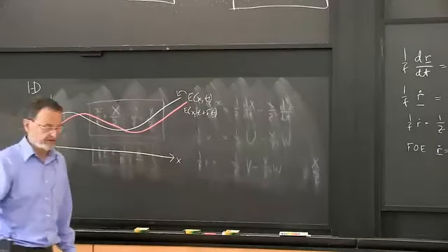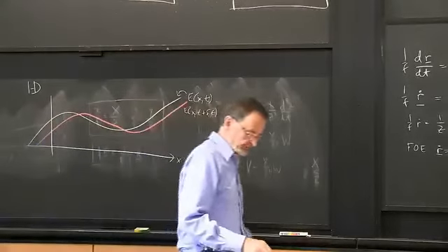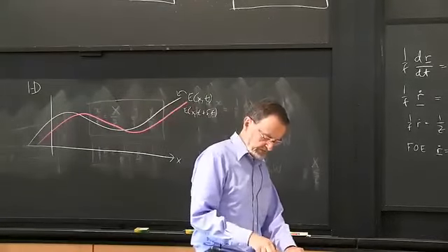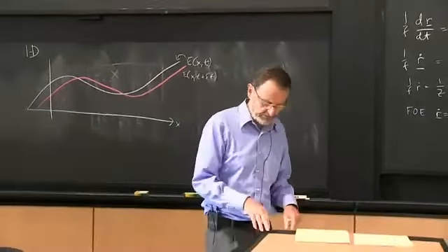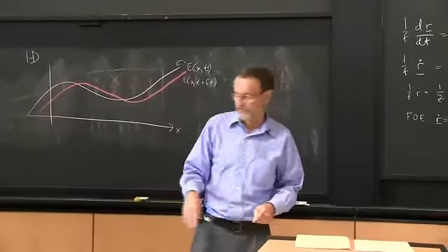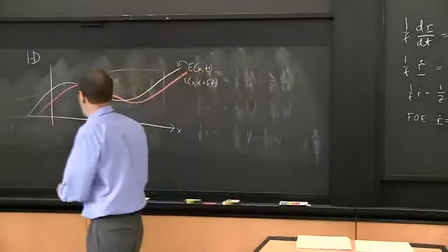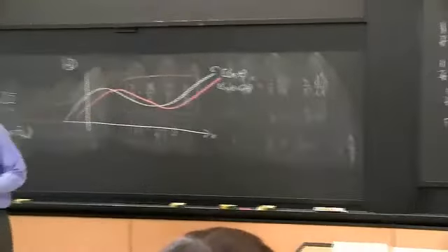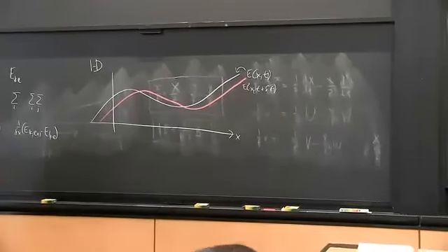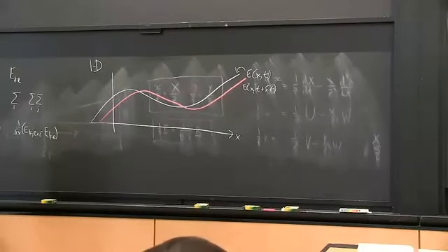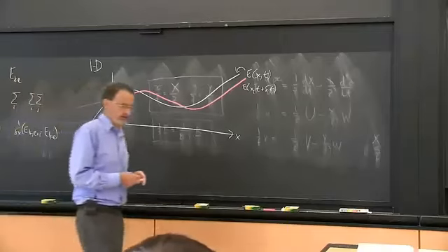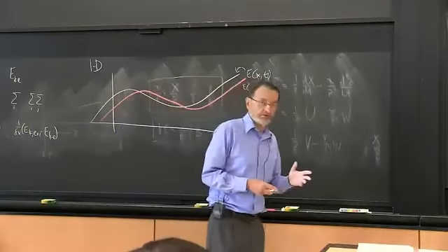You're holding it down on the table. It has a short focal length lens that's imaging the surface of the table, and if there's some texture to it, as there is on the wood over here, then that texture is mapped onto the image. And if you move the mouse, then the image of that surface will move. And your job is to accurately estimate how fast it's moving.